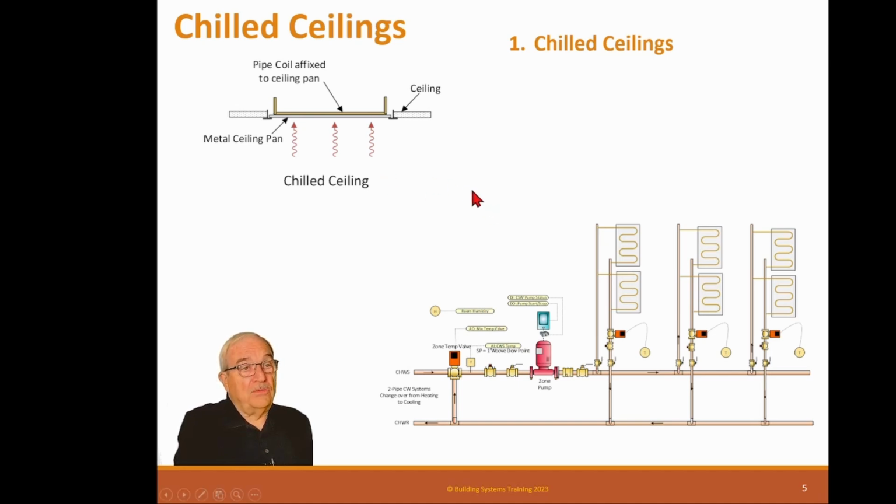So when we first started using these, we had a little bit of a problem, in that we didn't have enough space to absorb. Now remember, these absorb only sensible heat. They don't absorb latent heat. So only sensible heat. So the idea was to have enough of these in the space to take care of 100% of the sensible load, and then you have a fresh air system taking care of the latent load. And normally the fresh air system we prefer was displacement ventilation. So we had that system putting the cold air on the floor with the fresh air required in it, and we'd dehumidify that air, so it would take up all the latent heat load, and these would take up the sensible load.